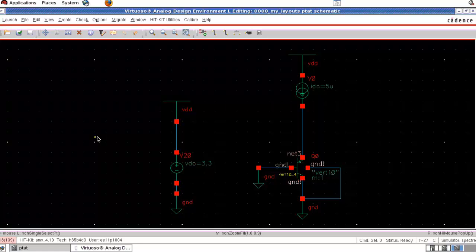We simulated our CTAT earlier. Now let us simulate our PTAT. So to get the PTAT, we said we need two arrangements. One is the voltage across a diode and the voltage across diodes connected in parallel. Then we subtracted those two voltages to get the PTAT voltage.